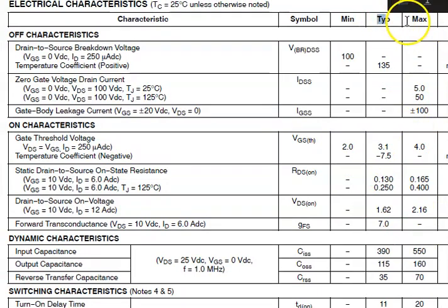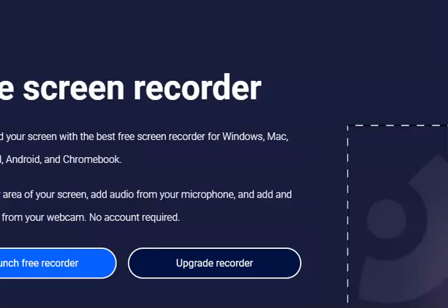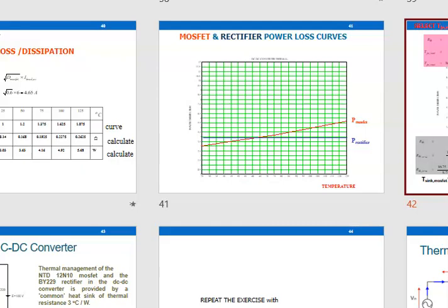So we can use typical, we can use maximum, either one. So in your design later, maybe we put maximum first. If it does not achieve your target, you can use typical. So if your target is achieved in between, you can pass, or you can allow your system to be marketed or mass produced. If not, you have to reject or select new items, new parts or a new design. Okay, so that's how the approach is.